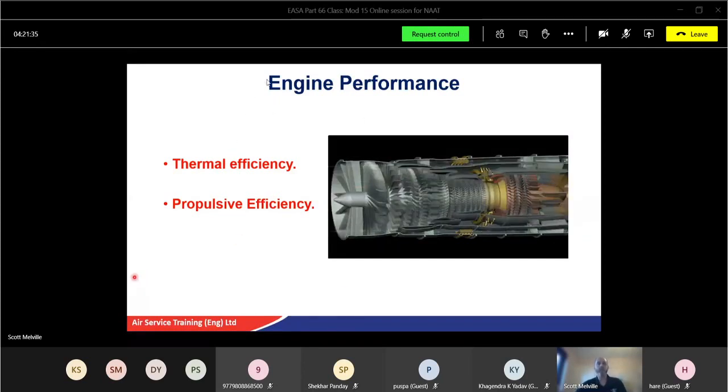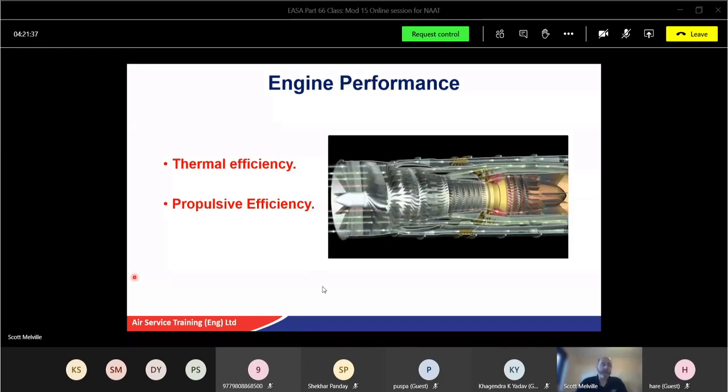Okay, we spoke back in the first few days about compressor efficiency, isothermal and adiabatic being ideal, where if there's too much heat loss through casings, we're not as efficient as certain other ones. Certainly a centrifugal compressor is not quite as efficient as an axial flow compressor. The axial flow compressor has a modular pressure rise through each stage, where a centrifugal one is one big pressure rise, a lot of heat, and a lot of heat gets lost as well.